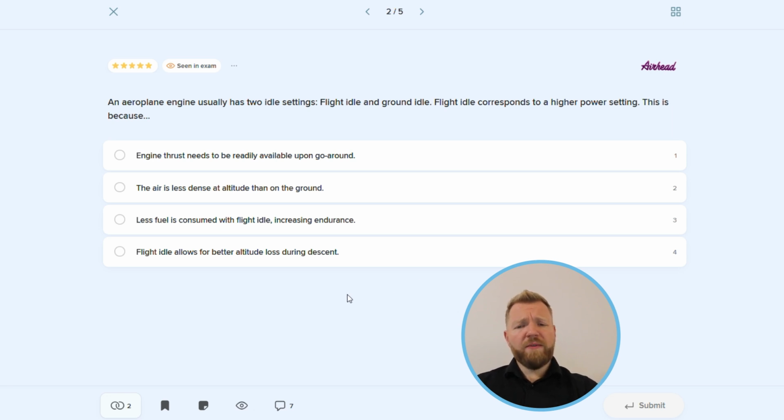Alright, so during flight, the engine operates at higher idle RPM to be able to accelerate quicker to full power. When you start your jet orientation course or MCC, you will see that the turbofan engine accelerates much slower than the propeller engine, where response from more thrust is almost immediate. This feature is especially pronounced at low RPM. Just imagine that on Airbus A320, the spool-up time from idle thrust to full thrust can take up to 8-10 seconds. It is kind of a protection for the engine. It protects from overheating, overfueling, or surging.